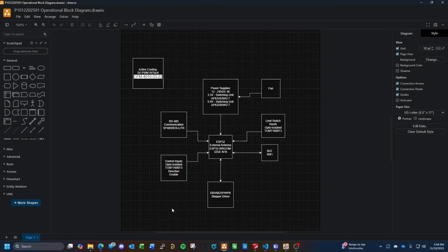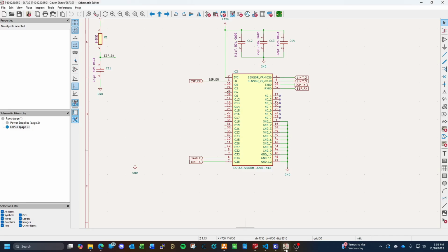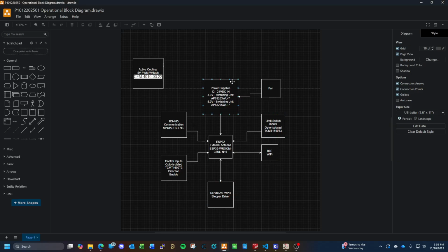For any of those who remember our last episode, we left off starting to throw in and define our inputs, some of our pin assignments on the ESP32. Now, I'm hoping that our ambitions as far as the block diagram we threw together aren't too great to where we don't have enough GPIO pins for everything, because the fan with the tach and the PWM input is going to take up two.